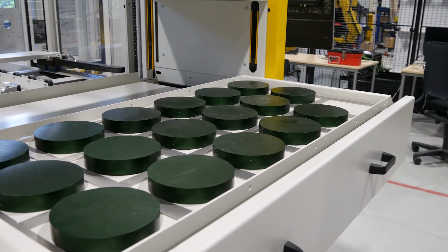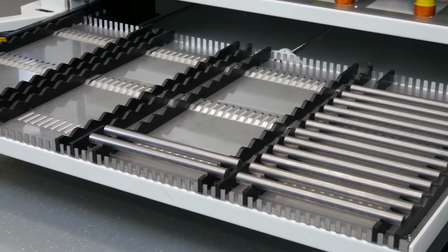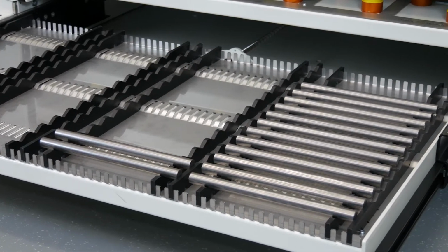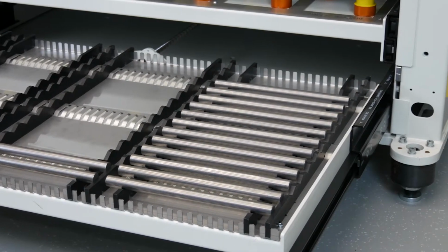Cylinders or discs are usually placed on a grid in the tray and picked with a 3-point gripper. Bars are usually placed on supports with cutout V shapes, which are clicked into the inlay, and the bars lay across these and are usually picked with a 2-point gripper. Now, there are many flow options, which I will discuss with you now.